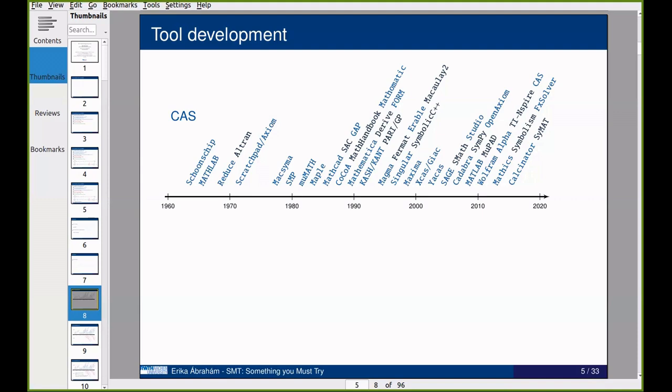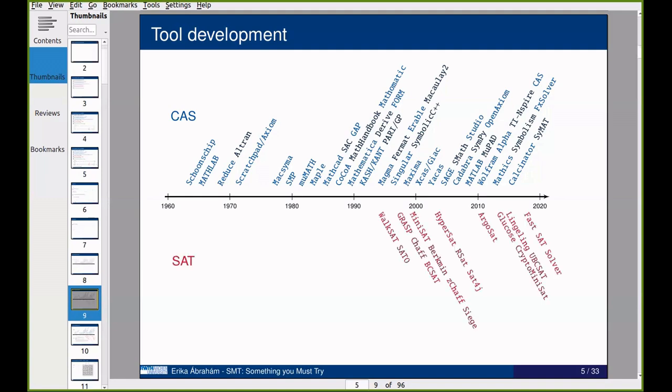But then the focus was more on the mathematical structures of these problems. And then in the 90s, something happened, and people recognized how painfully expensive it is if there are bugs in hardware. So also driven by this strong need of industry for verification techniques, SAT solving arose. SAT solving is a technique for propositional logic, and propositional logic is able to describe properties of discrete systems and in this sense also of circuits. So, for example, bounded model checking is one technique where you can express the existence of bugs. And these are logical formulas in propositional logic.